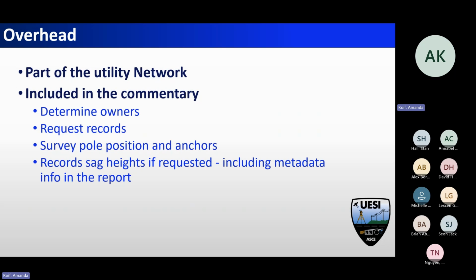The sag heights, I know TxDOT Dallas, anything that's crossing a road now, you have to have the sag heights associated with that utility plan. You may request it along the parallel piece for sound walls and other pieces that may be affected. The poles are usually at 3 foot. If you want to put a sound wall at 3 foot, well, you probably need to know how tall that sag height is, or if those poles or sound wall need to move because there's not enough clearance between those two.